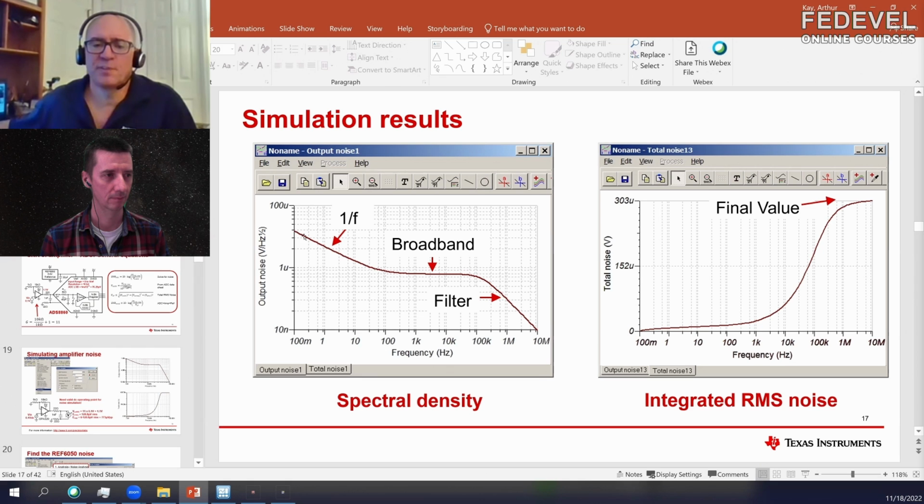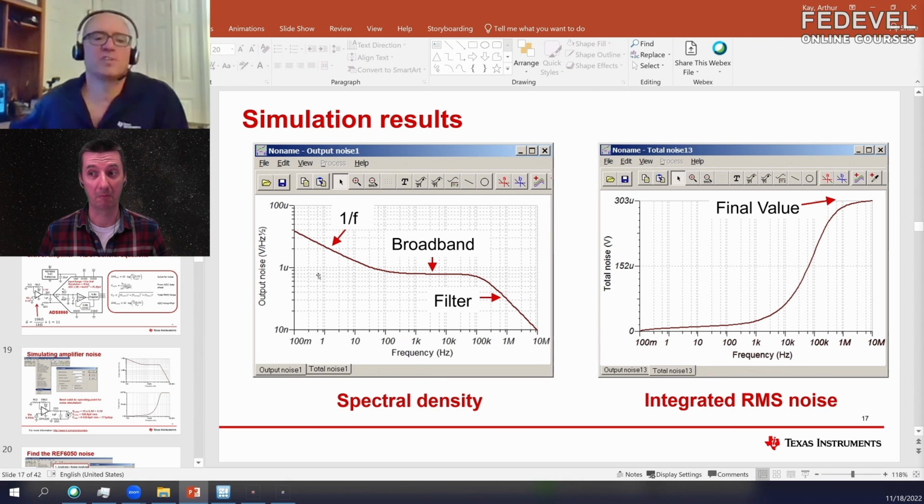And it's difficult to filter this 1/f out. So people who are doing very low frequency measurements want to make sure that they don't have this 1/f. Some amplifier types actually have no 1/f noise, called chopper amplifiers or zero drift amplifiers. They flatten out this region by doing an internal calibration, and they also have good properties in terms of temperature drift, so the temperature drift is very, very low. Because the noise is changing over 1 second or 2 seconds or 3 seconds, they shift the zero and move with this noise. Oh, okay. Wow.